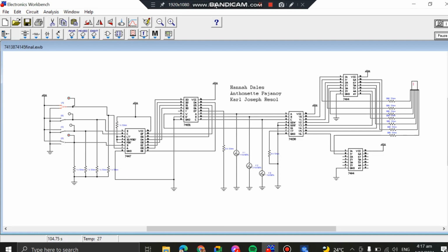In addition, all LEDs in the 7-segment display are blinking one at a time following a certain pattern, depending on the connections between the output of the 74138 IC and the segment display, which are connected by two 7404 hex inverters.